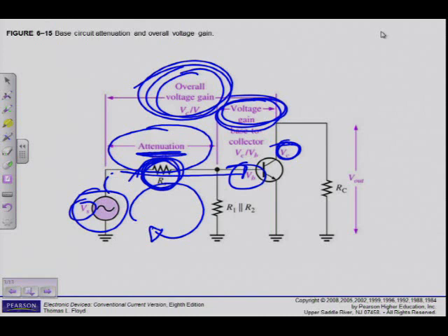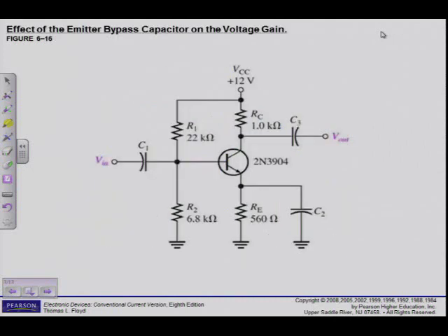So in the lab, for the amplifier that you're going to build there as well, you're going to use the signal generator as your input signal that you want to amplify, and that information is available. You will see on the output of the audio amplifier or the signal amplifier, it's actually written there what the value of RS is, the output resistance or the internal resistance of that device. Alright, then the next section, the effect of the emitter bypass capacitor on the voltage gain.